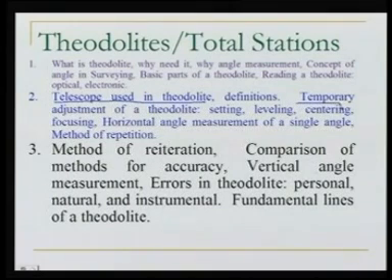Then if you are going to a field and we want to measure an angle, we saw the procedure last time. So there are some steps which we need to do at every station. These steps are called temporary adjustments. We take the theodolite along with the tripod to that particular point, or we can say survey station. Then we need to do a couple of things. Number one is centering. We put our tripod over that point and approximately center it. Leveling, we level the tripod head approximately.